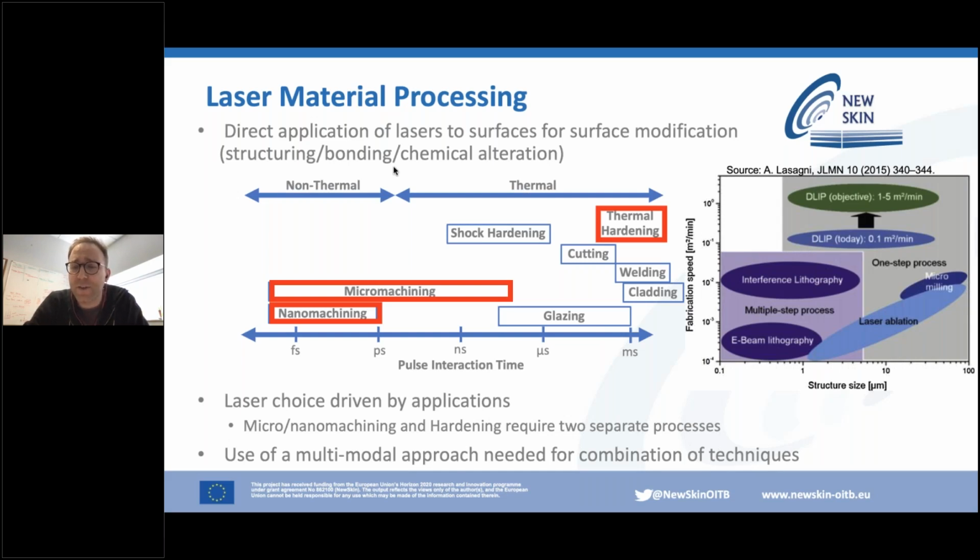And in terms of laser ablation as a manufacturing process, it's very adaptable. As you can see on the right-hand side, we can produce structures from micron-sized all the way up to tens of microns or hundreds of microns or millimeters. Or we can extend this even below the single micron to the nanometer scale, which makes it a very competitive technique, and fast as well, when compared to some techniques for this sort of precision micromachining.